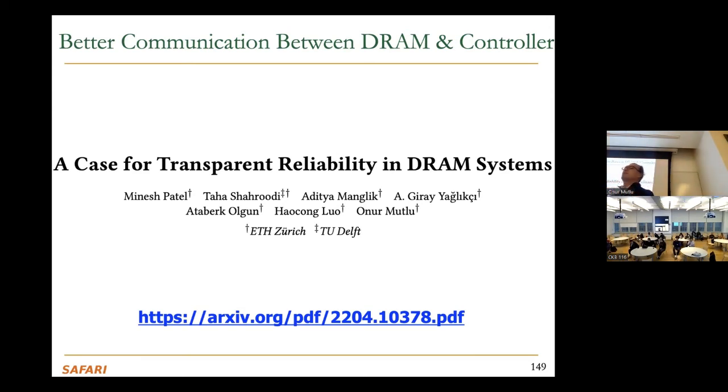There are also lower level mechanisms that people have proposed that are not used today, like bit level repair mechanisms that require some programmability in the DRAM chip or the memory controller. But it's a similar idea, basically. You either offline the row, take it offline so that nobody uses it, or you remap the vulnerable bits to somewhere else. Yeah. That's a very good question. I think we need to look at those mechanisms going into the future more and more as things become more vulnerable.